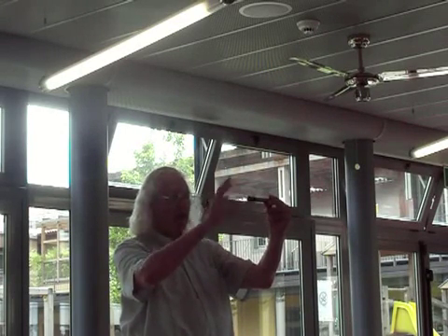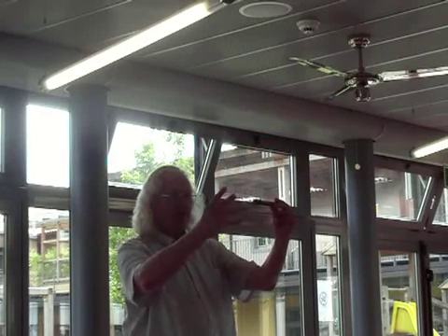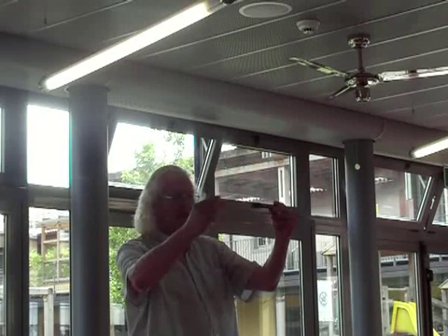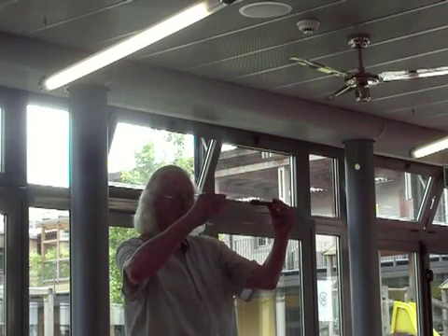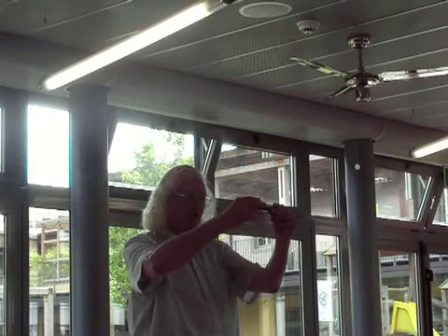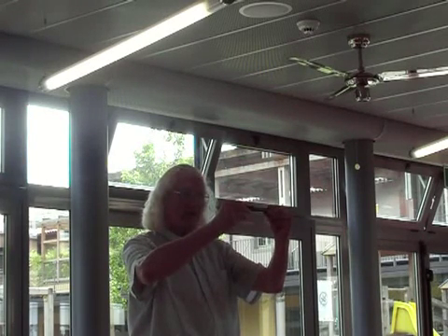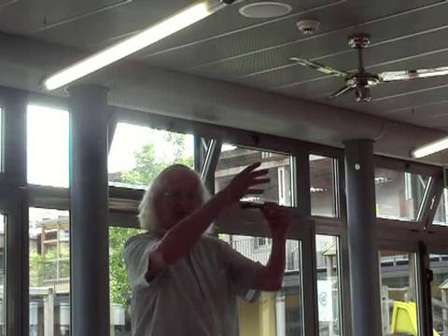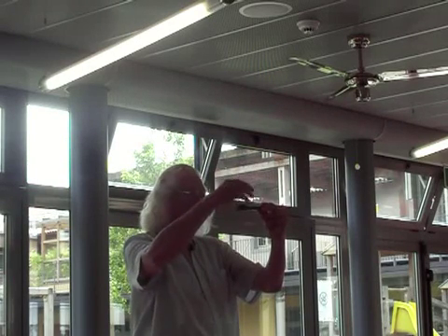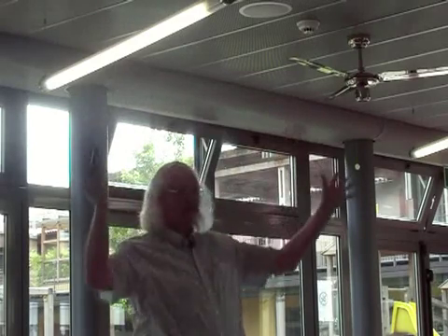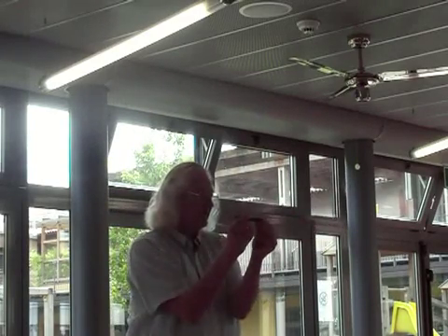And so now the yield surface has grown and has become twice as large. So if I were to pull this first in tension, and it yielded at a stress of 20, and then I went back to 0, and then I twisted the bar, it would yield in torsion at a stress of 20, not the original yield strength of 10, because I've hardened this in all directions. Right? So hardening happens in all directions at once.